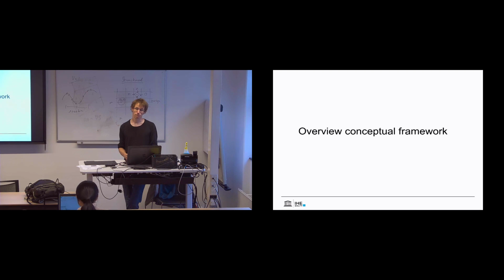Can we shift, if we started with one of them, let's say with the FM, and we figured that it's not good enough, can we just convert it or send it to 3D? As long as parts of your grid are curvilinear, yes, you can always change the grid. But you will then have to use domain decomposition to actually merge the domains together into one model. And if the grid is not curvilinear, no.